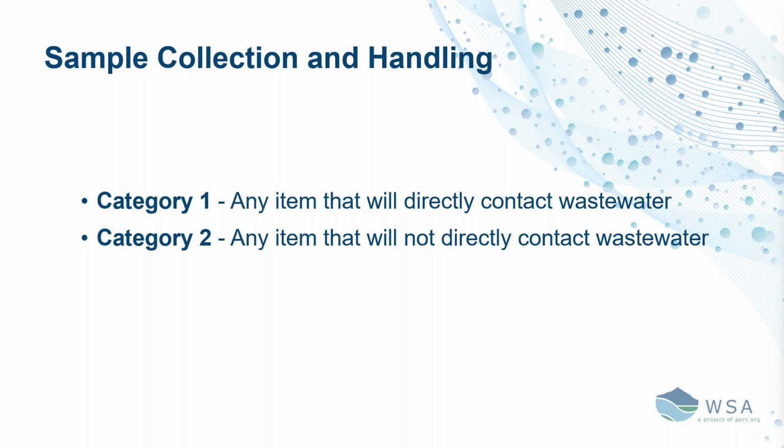And I always try to get as much sampling equipment when it comes to the bottles, water, lab grade water, or the deionized water in this case, as much as possible from the lab. It does cost a little bit more, but at least then you know for sure what you're getting from your lab is PFAS free. And whenever I have something that comes back in the form of skewed data, I always look at myself first and see, okay, what did I do wrong, or did I do everything right? So I always try to get as much as I possibly can from my laboratory.